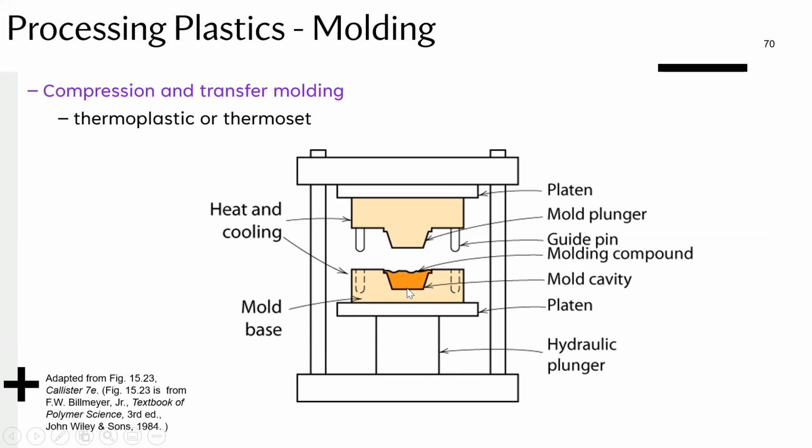You put it here, and then you cross-link it into a polymer. Now that part that you've obtained there cannot be reversed. That's the point. So you can always take it from monomer to polymer, but once it's reached a polymer state, you can't reverse it. So what's interesting is that for thermosets, the polymerization actually happens here. Okay, so that's the unique part of it.